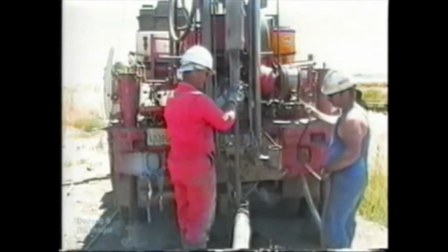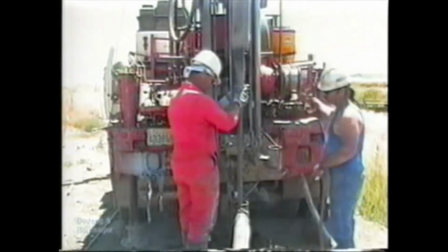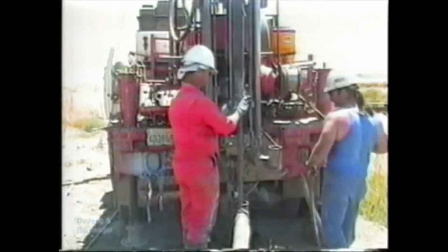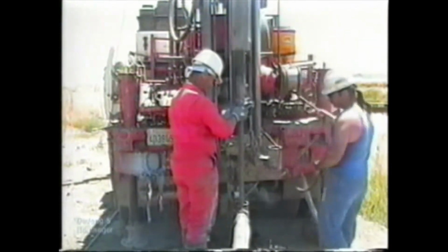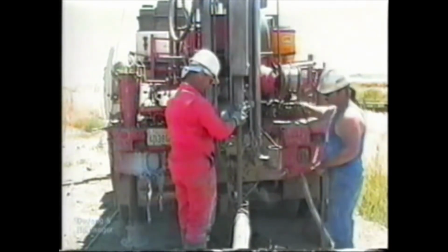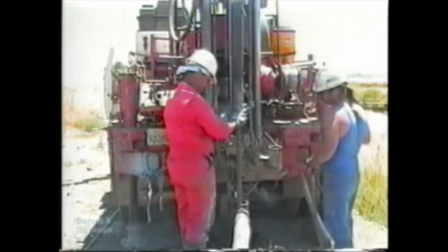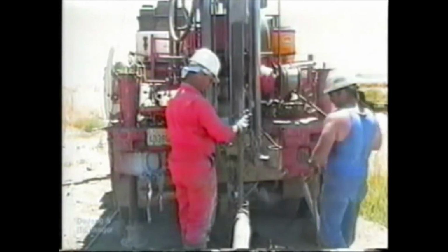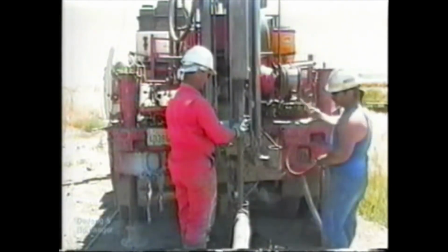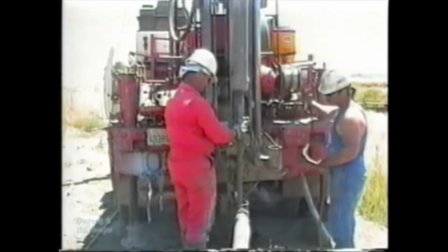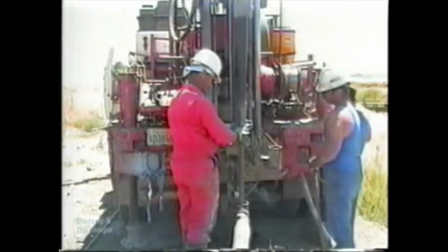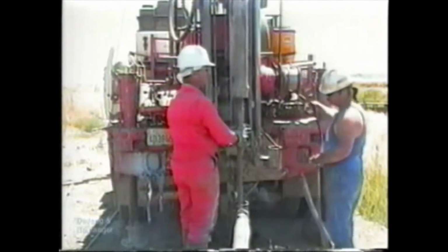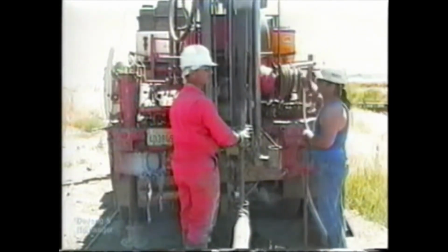Generally, the better the quality of the sample, the more expensive and time-consuming its recovery is likely to be. For some purposes, such as designing the foundation of a light structure on stiff clay, the expense of obtaining high-quality samples may not be justified. On the other hand, when the compressibility or shearing strength of soft clay is needed to evaluate the settlement or stability of a critical embankment or structure, even the best samples may barely be adequate. Consequently, there is a need to establish a quantitative measure of the quality of samples, especially for soft clays and